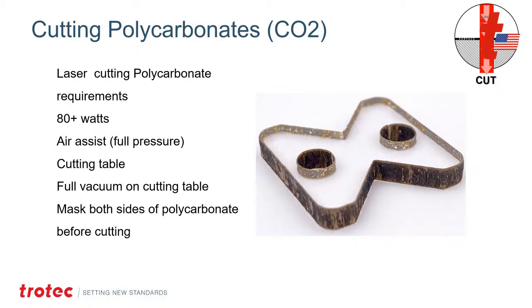It does require a lot of laser power. Air assist with full pressure when cutting, and a full vacuum cutting table. So you'd have the cutting grid with the vacuum underneath of it, blocking off all excess, because it does produce a whole lot of smoke and residue, which I will show in a video next.